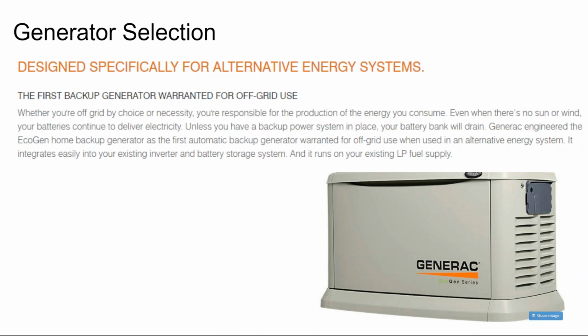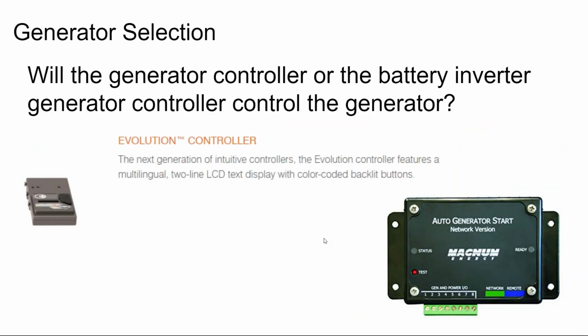And so to some extent, having a dumb but controlled generator is better than having an intelligent generator that may have its own brain and go off and do something that you don't want it to do, like not overcharge the batteries, which you need to do as part of your battery maintenance. Right out of the box, you can tweak the settings, but our renewable generator was not wanting to equalize our batteries.